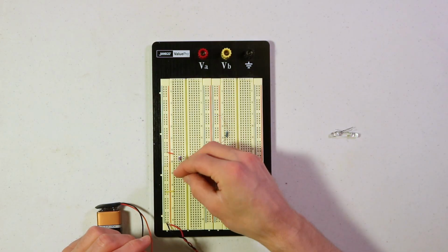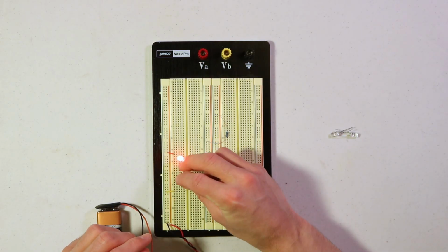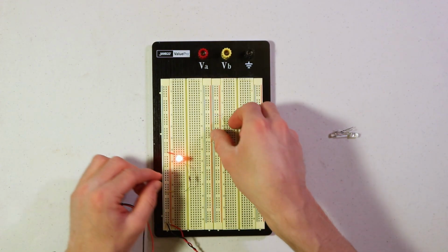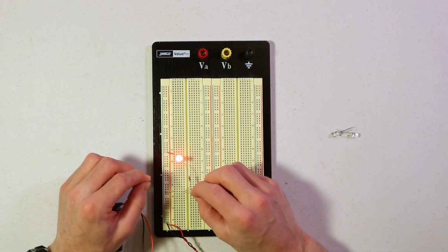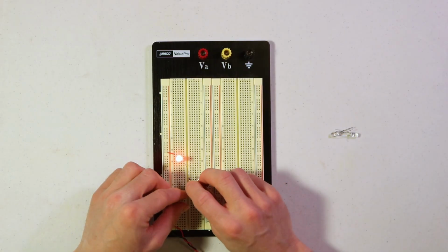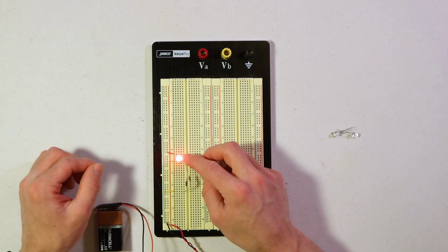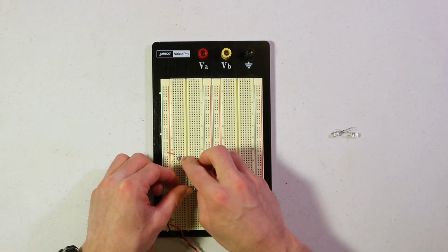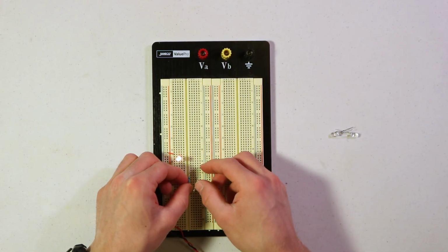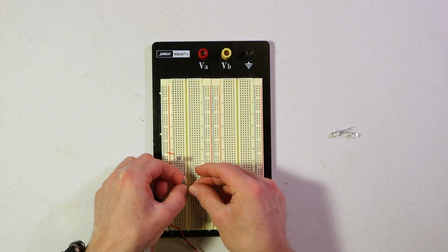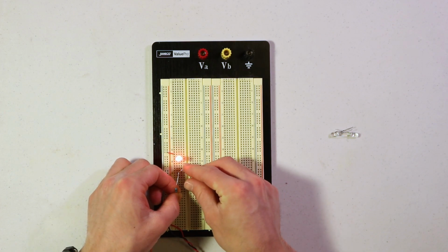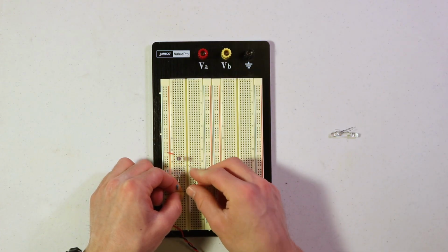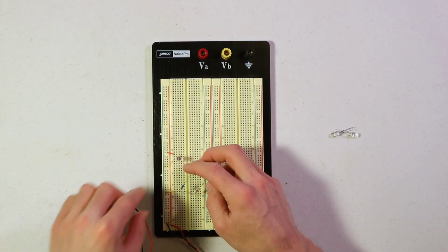If we put that in and swap it out for the other resistor, now you can see the light is a lot brighter. So again, just for comparison, I'm going to put one end of the 5.1 kilo ohm resistor in, and then if I pull this one out and put this one in, you can see it's much dimmer than when I just had the 470 ohm resistor. So the 470 is a lower resistance, it gives a much higher current and a brighter LED.